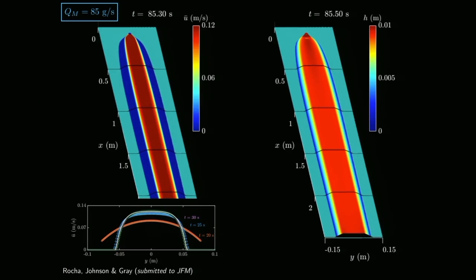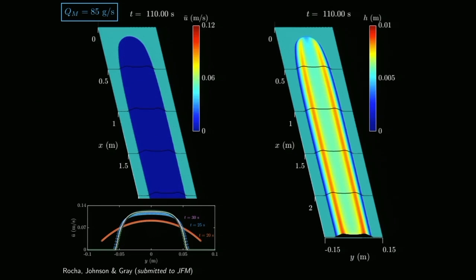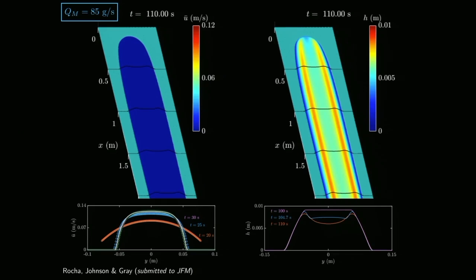When the levee is formed, the velocity profile approaches the steady state solution, which is this exact solution, this white curve here. When the flow has ceased, the channel drains out, leaving behind the fingerprint of this channel-levee morphology. If we look at a cross-slope thickness profile, we have this constant thickness. During the drainage, the motion is just in the center of the channel, and you have a deposit, the super-elevated levees, which is linked to the thickness of the channel. So we think that if in the field you measure the height of this deposit in natural flows, you can infer something about the previous motion.